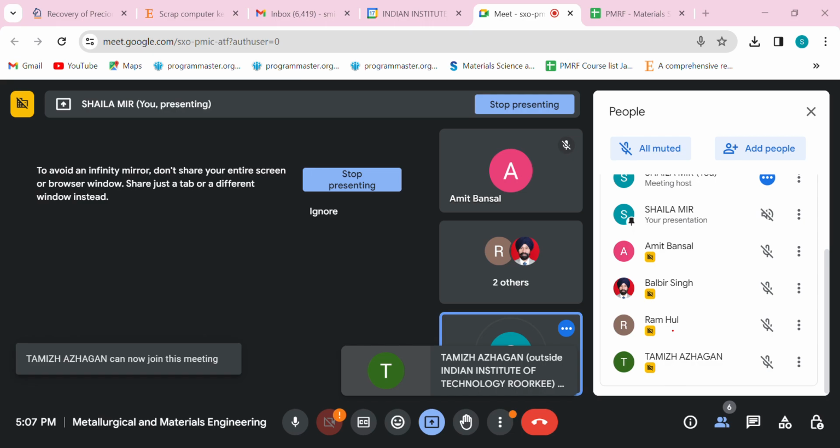This is actually false, right? Because it becomes horizontal after a certain number of fatigue cycles. That means you can put the sample through that specific number of fatigue cycles, and the material will not fracture. So this is, for example, for steel, and this is for, say for example, aluminium. So this is your typical SN curve.